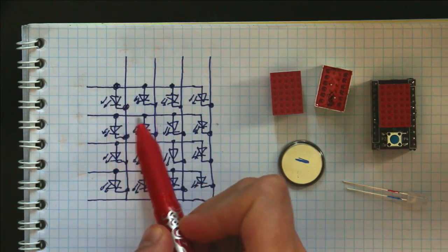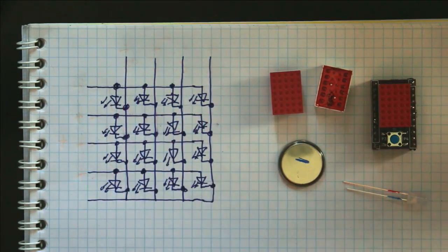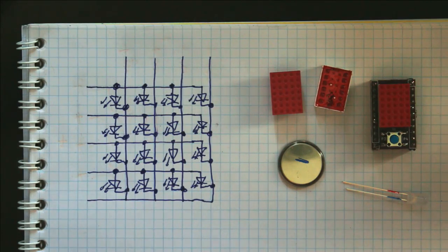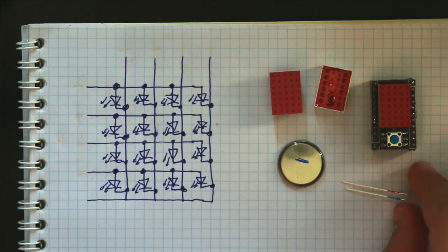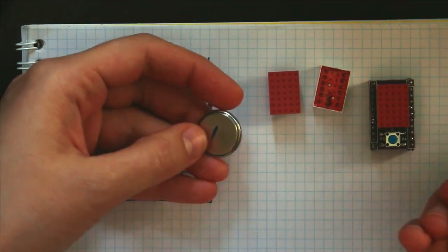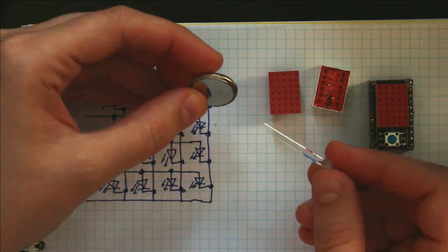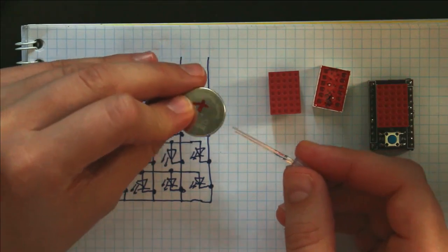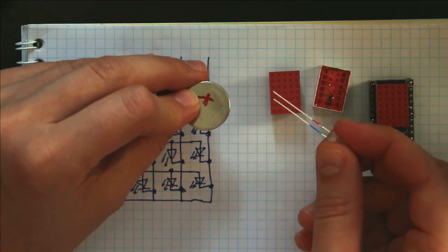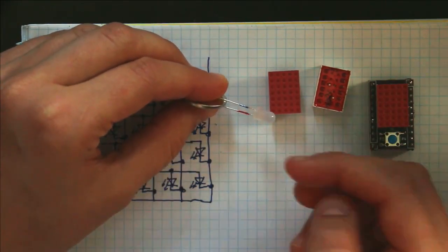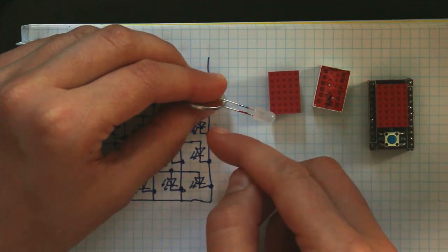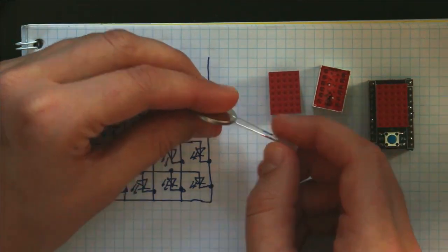So in order to understand how to work with one of these, we need to know a little bit about how LEDs work. And an LED is basically a one-way valve for current. In other words, it only allows current to flow in the direction of this arrow part of the diode. And to demonstrate that, I have just a regular LED and a coin cell battery. And I've labeled the negative side and the positive side of the battery and of the LED. So if we connect it backward, nothing's happening because current is trying to flow in the wrong direction and it won't allow it.